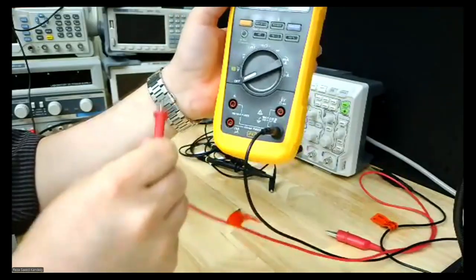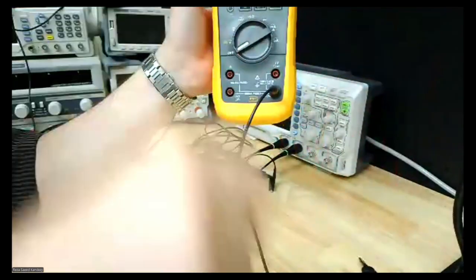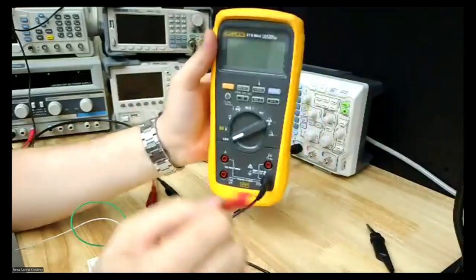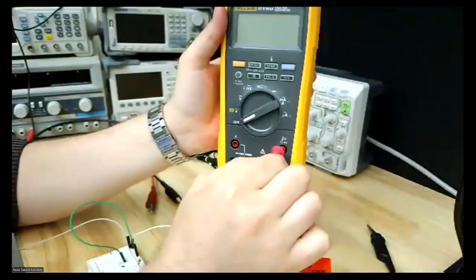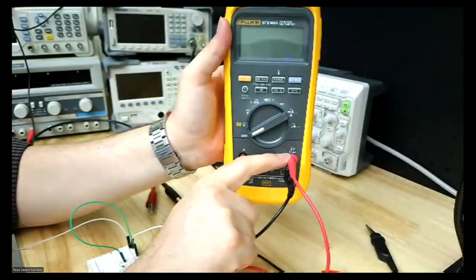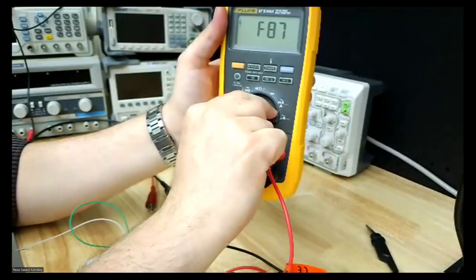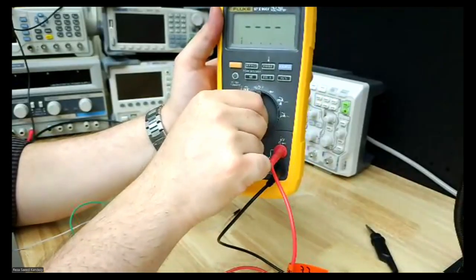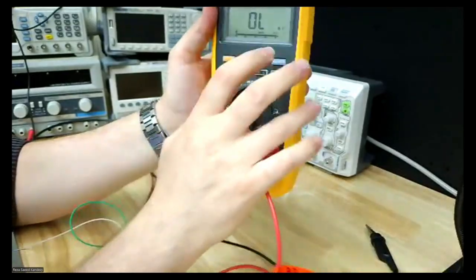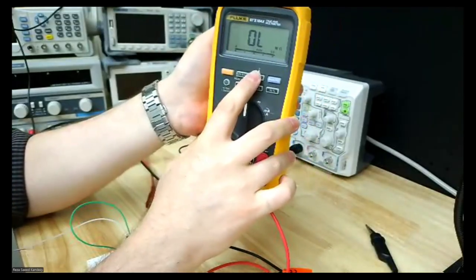Okay, now we wanted to first see if our 1 kilo ohm is actually 1 kilo ohm or how much tolerance it has. So I'm gonna connect my measurement probe to the socket dedicated for ohm meter. I'm gonna turn on my multimeter and put it on the ohm setting. Okay, and I'm gonna choose the range. I'm expecting a 1 kilo ohm, so I'm gonna change the range.